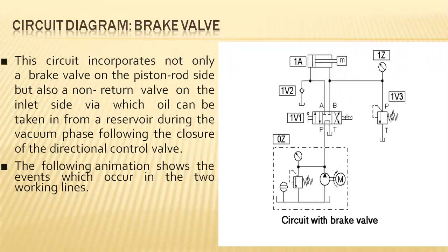And next, we'll be having a detailed look at the utilization of this pressure relief valve as a brake valve. So, brake valve. Here we'll be having a detailed look at this pressure relief valve used as a brake valve. The circuit which is displayed here incorporates a brake valve on the piston rod side. So this is the piston rod side, the actuator, the cylinder piston arrangement and piston rod side. The pressure relief valve is fixed here.